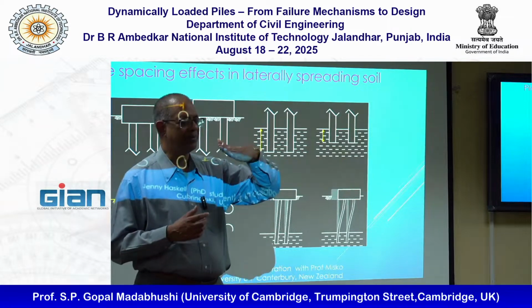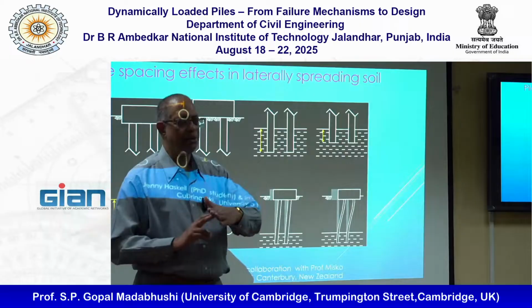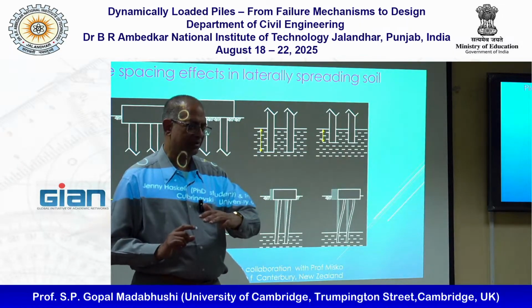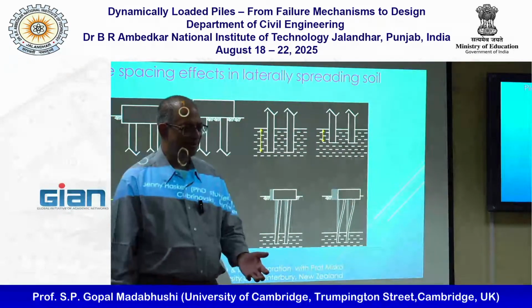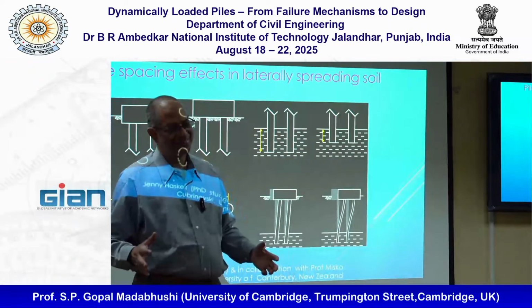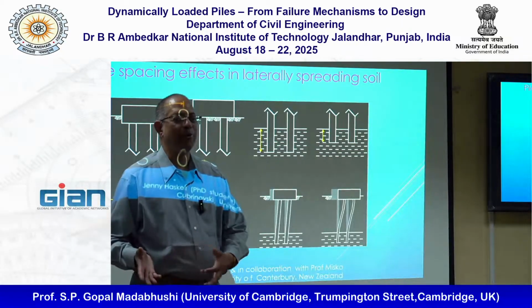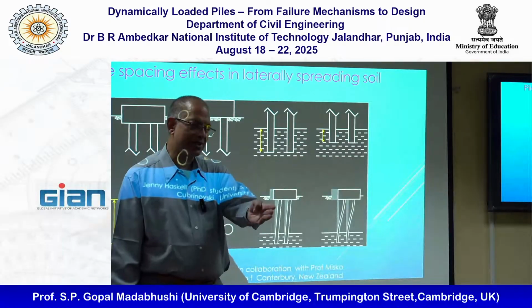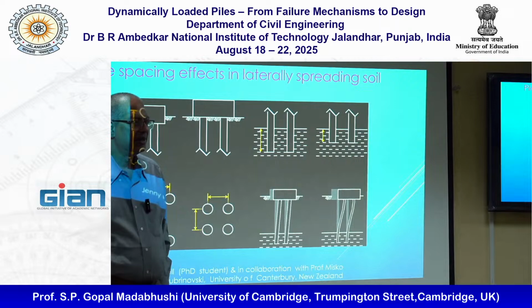Basically, if the raft is going to bend, then the pile also needs to get pushed down, and you work on that strain compatibility between the pile and the raft. Again, most of the stuff Mark Randolph has done is to do with imagining all this is elastic. Yeah, we know the soil is not elastic. Therefore, there's a lot more work to be done, even for static, which he had a bunch of students and he did quite a lot of work on that.